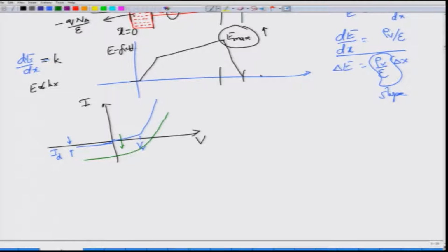So what you see is this type of graph. This is of course exaggerated pretty badly. What you can see is that the V gamma, the cut-in voltage that you would have seen for the photodiode without any illumination, would actually become larger and larger. At the same time, the reverse current will also keep increasing. This is the IV characteristic of a photodiode. Of course, you have to understand that the scale here on the positive side is in milliamperes, whereas the scale here is in microamperes.